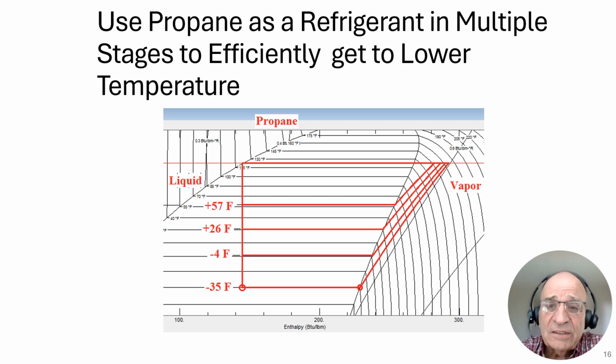And when is water used as a refrigerant? In an absorption refrigeration system. We're not covering that in this course, but in absorption refrigeration, water is the refrigerant, and it runs at a vacuum, a very high vacuum. In doing that, it gets the water to low temperatures in the 30 to 40 degree Fahrenheit range. But to go lower, you have to get to very low temperatures.